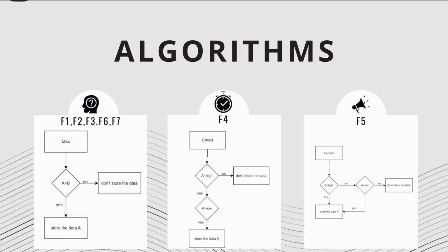Regarding function 3, calculating the average, we have a different approach. To avoid using a division operator, as it would significantly increase the area due to bit count, we decided to increase the bit count for storage, adding up the values and considering the first 12 bits will yield the average of 8 items.